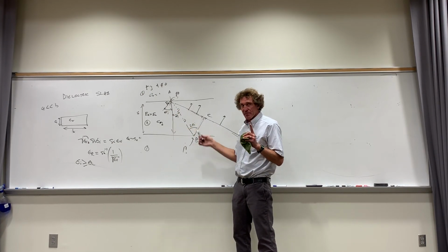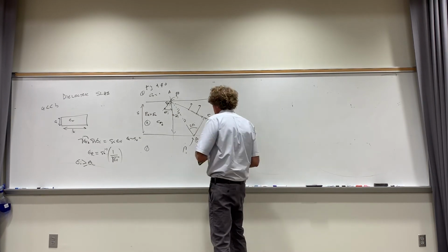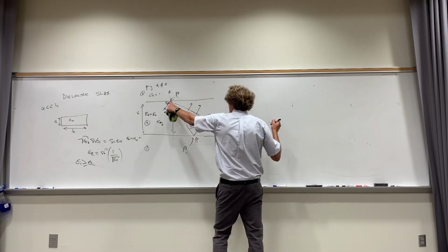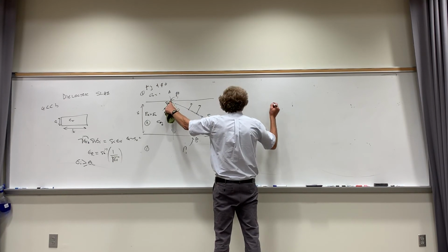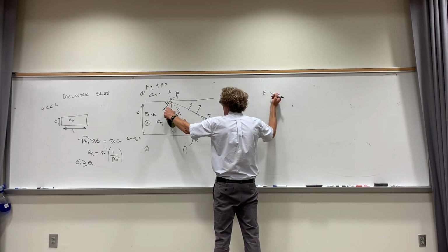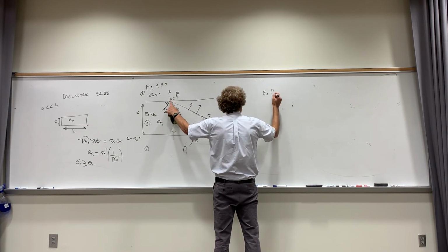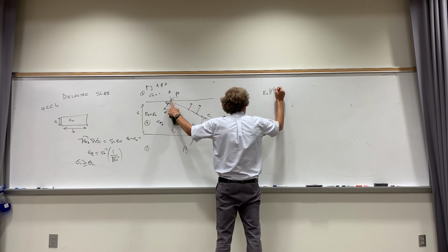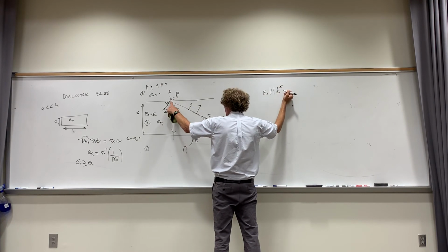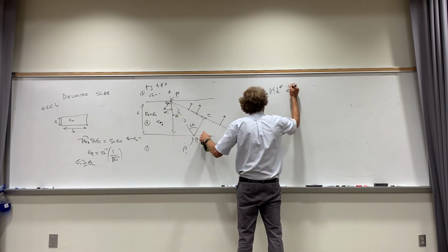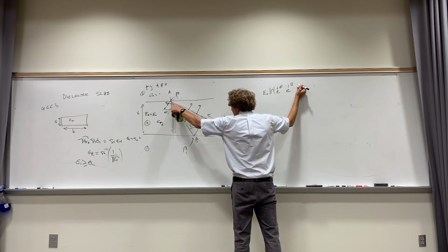So what they do is they'll say, well, I'm going to have E0 here. E0 times gamma is right here, and gamma is going to have magnitude gamma e to the j phase angle associated with gamma. Then it's going to be e to the minus j beta, and it's going to be this length.